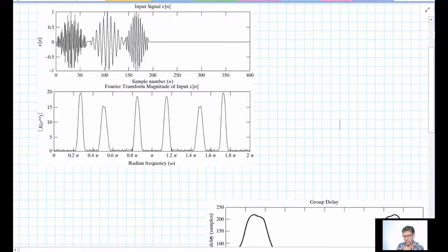And so what we see is that we have a low frequency, a mid frequency, and a high frequency. And so looking here from 0 to pi, then beyond that we just have the negative frequencies that are our virtual copy of the frequencies. And so the low frequency would correspond to the second tone, the mid frequency to the third, and the high frequency to the first tone.